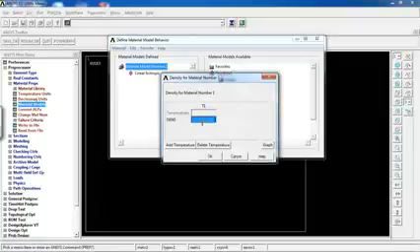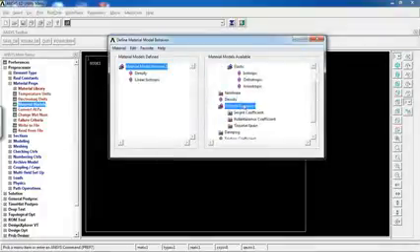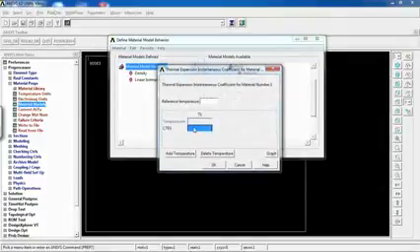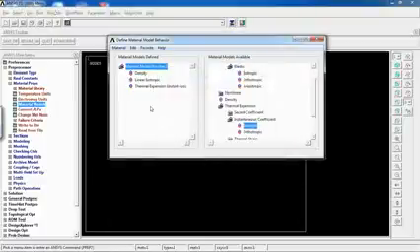So I double click on density, give the density of 7800 for the material, and I come to thermal expansion, instantaneous coefficient, isotropic, and pick again 13 times 10 to the minus 6, and OK this window.